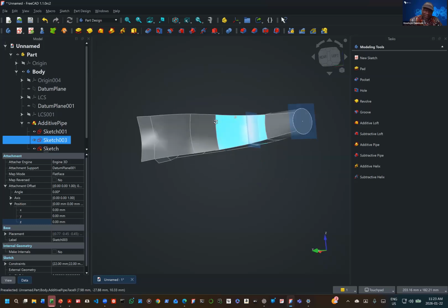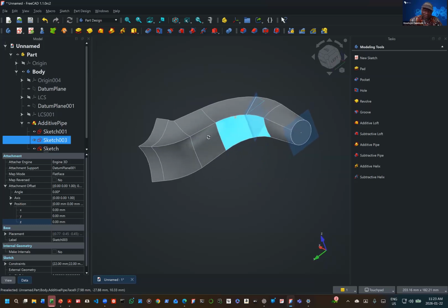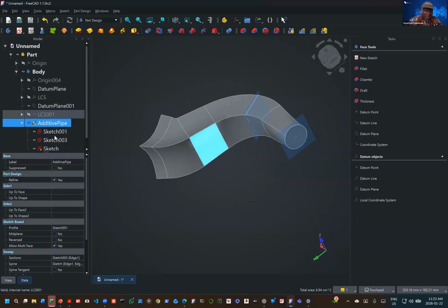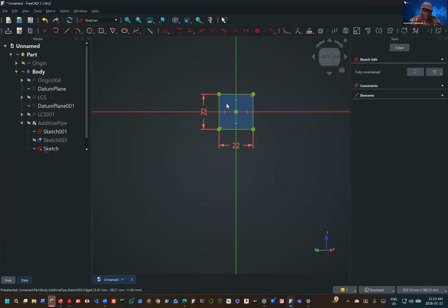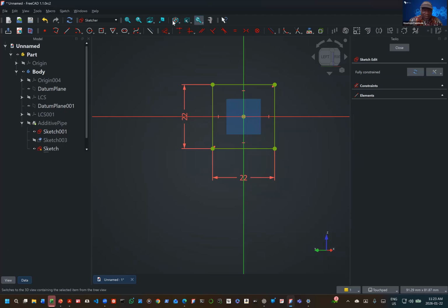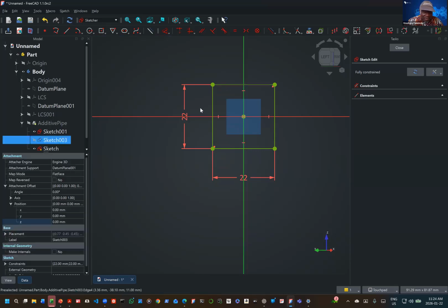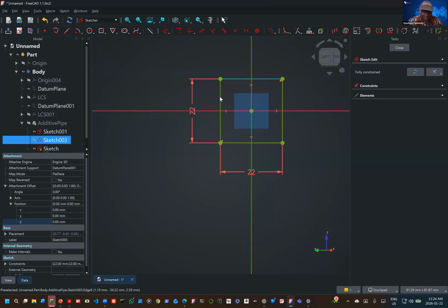We can round the edges of the square as we did before. We can round its edges, edit that sketch again, and round its edges. If we want to round the edges, let's see whether that will help. I can take the edges, and I can take this and this and this and this and this. Let me see whether I can do my filleting all at once.